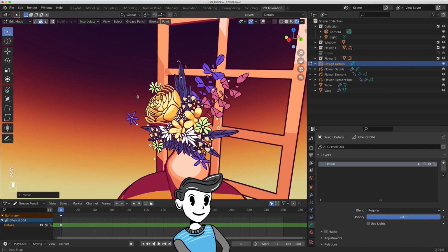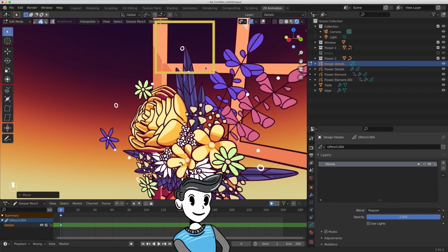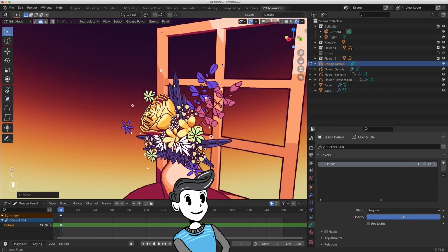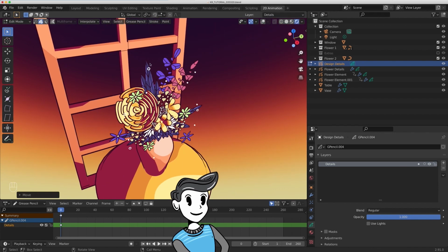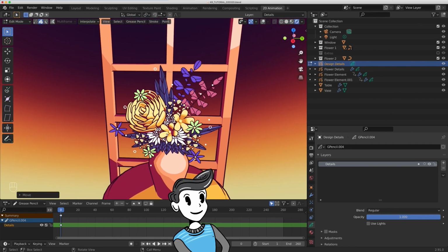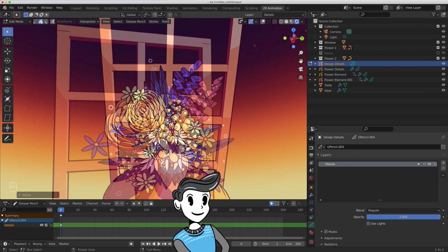Notice how right here, there's some glitching going on. It might be because there's another grease pencil object in proximity. To avoid this, I generally keep distance between grease pencil objects, or merge grease pencil objects together, which I'll demonstrate later. Now it's time to add the glow effect.